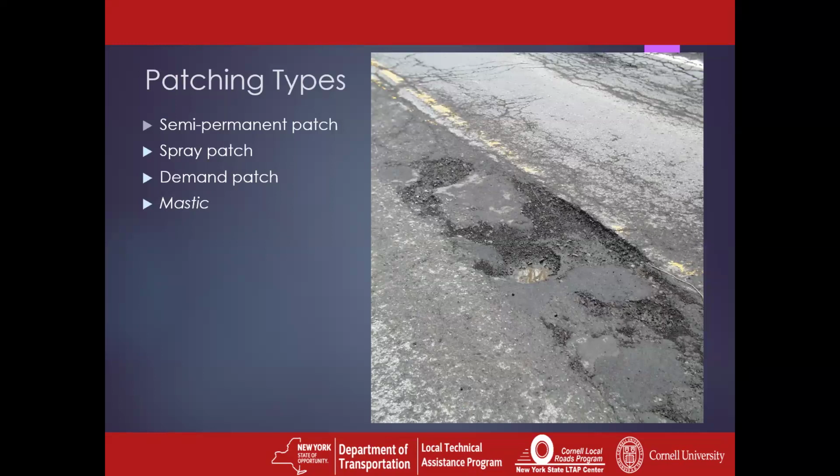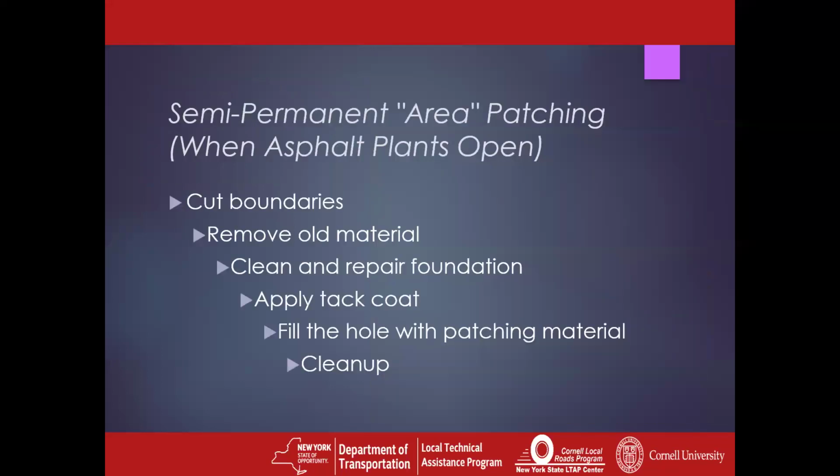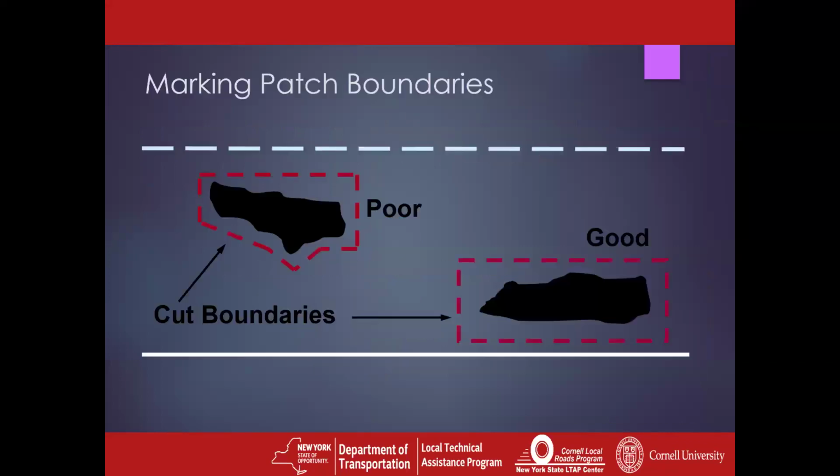In terms of semi-permanent patching, we do it when the asphalt plants are open. Cold patching is a technology that's starting to get a little more use in nasty weather, and then we use mastic patching, which is continuing to grow in use in Europe.